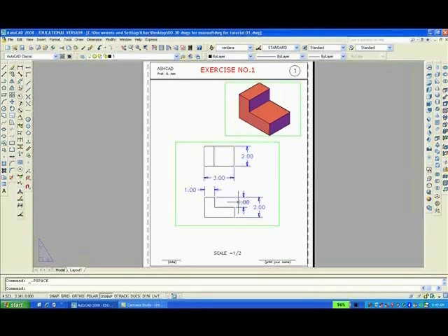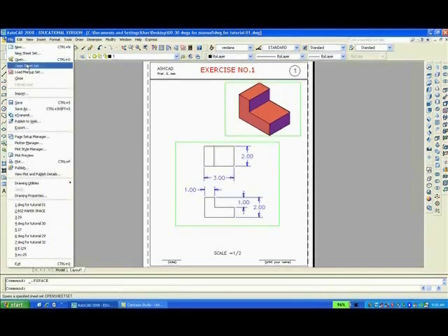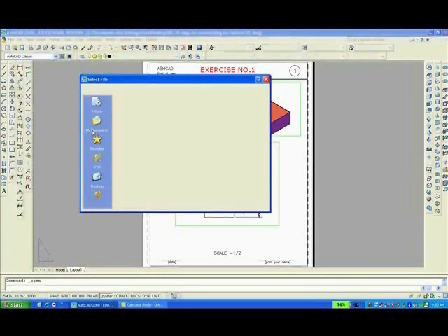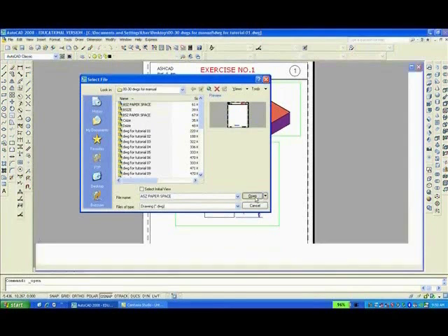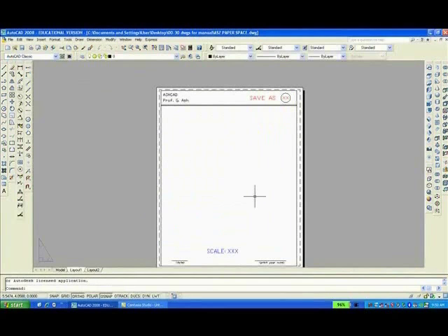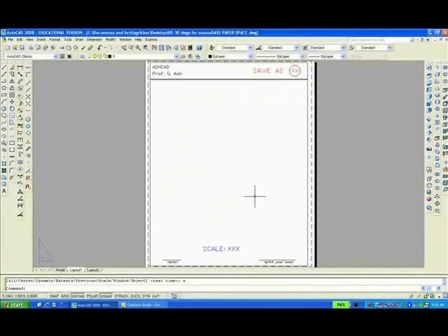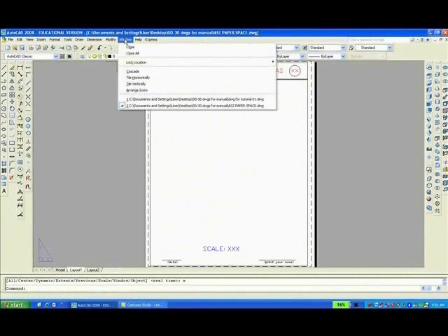drawing. The first thing I'm going to do is to go to File, Open. I want to open a drawing which I created called A-Size Paper Space. You'll be drawing on that mostly. I'll open it. And Zoom extents, Z enter, E enter. Next, I'm going to the Window menu, and I'm going to tile both drawings vertically.